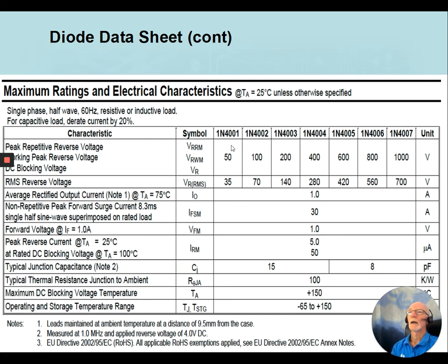Here is our range from 1N4001 to 4007. We can see that the breakover voltage varies for each one, but the other characteristics are the same. They are all able to handle 1 amp, for example, which is what we're particularly interested in. So if we were using this type of diode on a small voltage, like a 12 or 24 volt circuit, we can use the 1N4001.